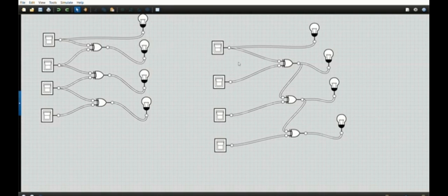These are code converter gates. This is binary to gray code and this is gray code to binary. In binary to gray code, we are using 3 XOR gates, and using these 3 gates, we are going to give 4 outputs. So in this, B3 is directly connected to G3, and this XOR gate uses inputs B2 and B3.